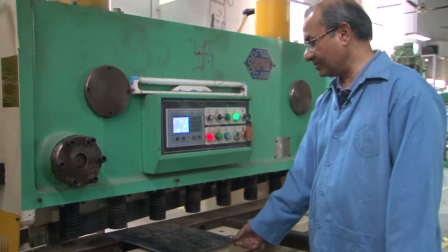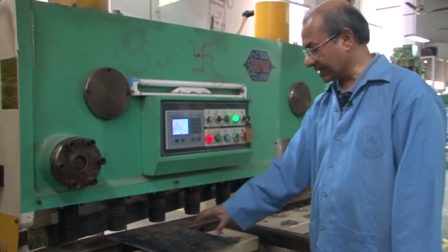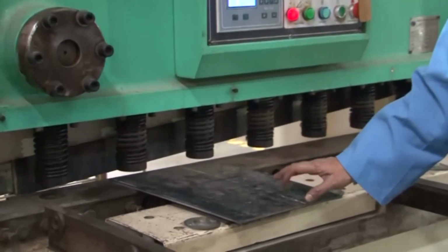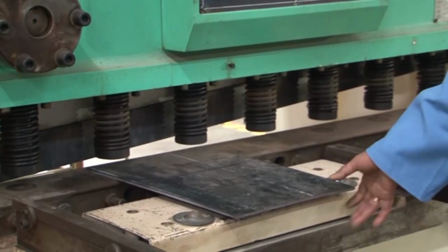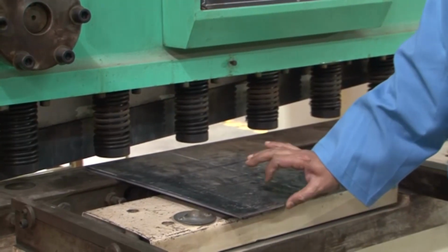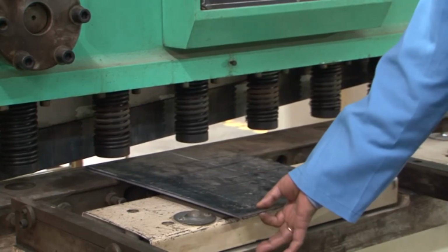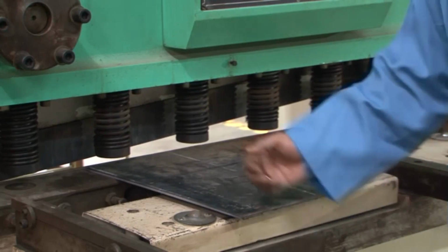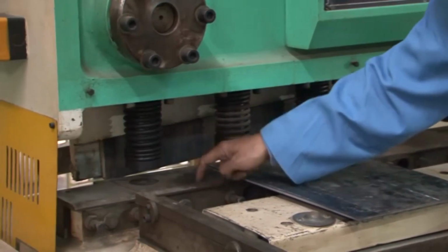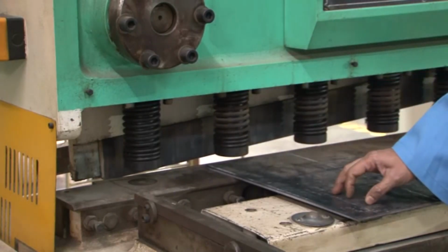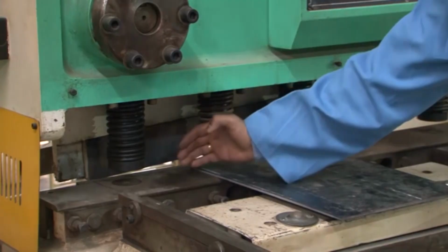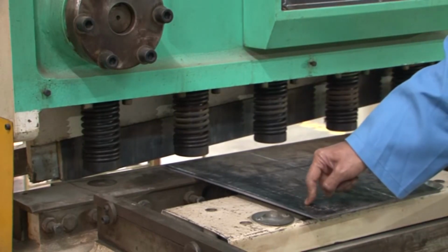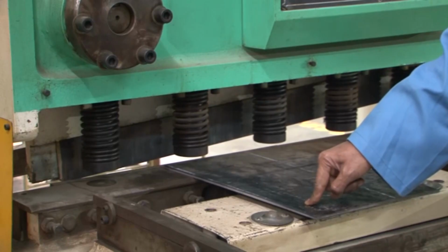So, right now we will demonstrate how this 6 millimeter thick steel plate, this is a mild steel plate, can be sheared off, and we will adjust the values according to the thickness of this plate. Now, what is the adjustment that we have to make depending on the thickness? If the thickness of the plate is smaller, you understand that the shearing force needed will be less, and therefore, the distance between this plate and this plate has to be less, and as the plate thickness increases, that distance has to be more. That adjustment has to be made by the handle there in the machine, and then the shearing process will be effectively performed. We will show it to you right now.